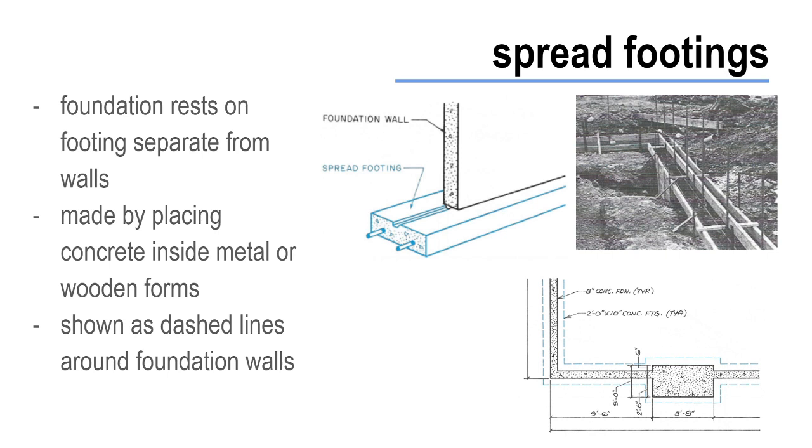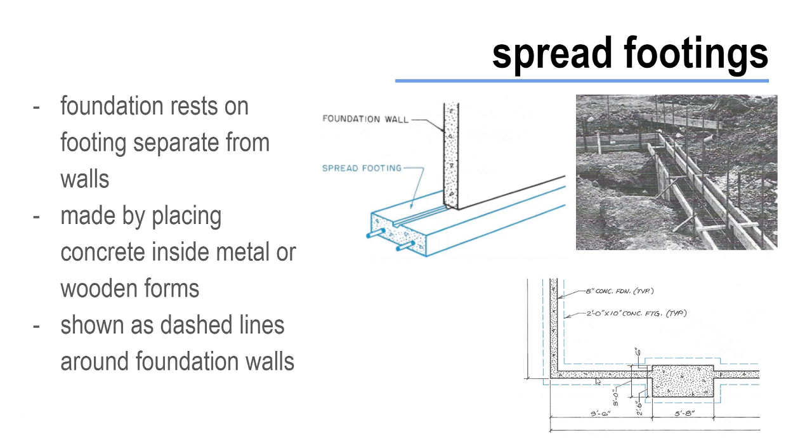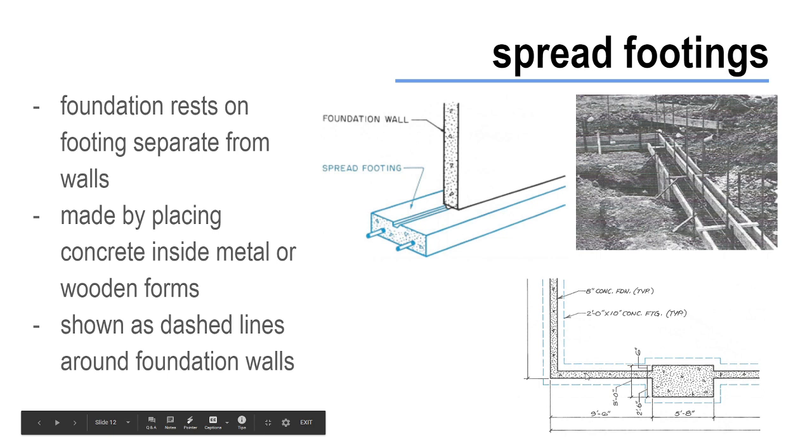In our plan, our footing is shown as those dashed lines going around the foundation walls. And the foundation wall is always centered on top of our footing. So the center line of that foundation wall is always going to be perfectly aligned with the footing itself.